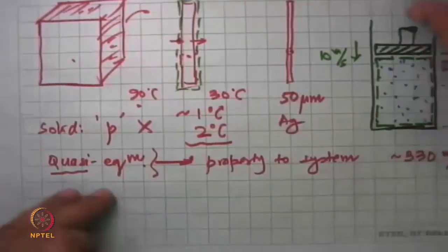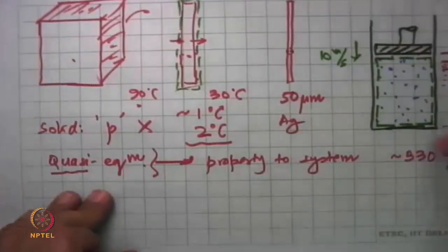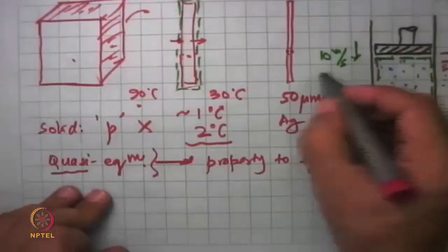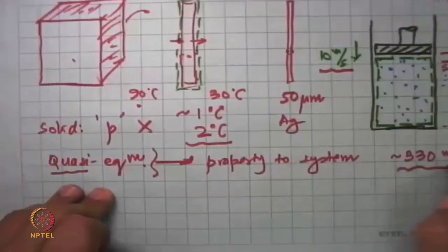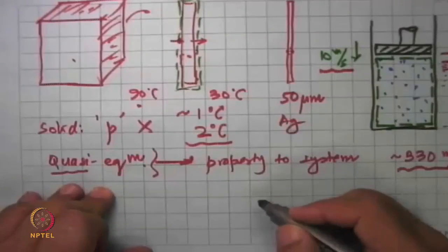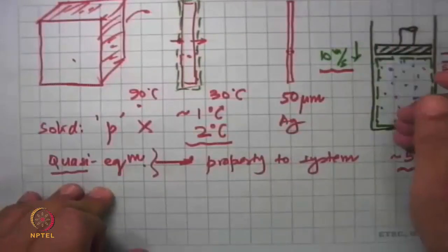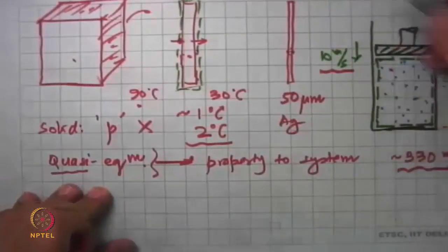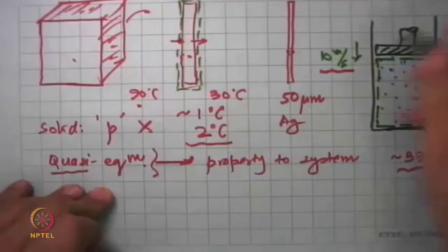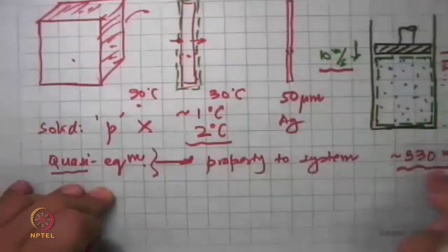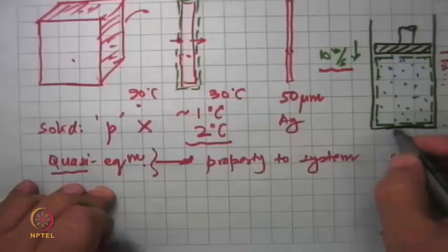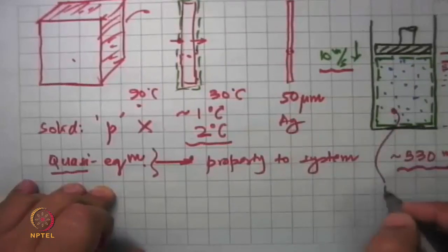Which means that as the piston moved, at a much slower rate, this pressure wave went through and equalized the pressure. The piston moves at only 10 meters per second, while the equalization takes place at 330 meters per second, so we can say the equalization takes place much faster than the piston moves. So during this motion, even though it is slightly not in equilibrium, as long as this velocity is much less than this velocity, I can assume mechanical equilibrium, and that's a decent assumption.